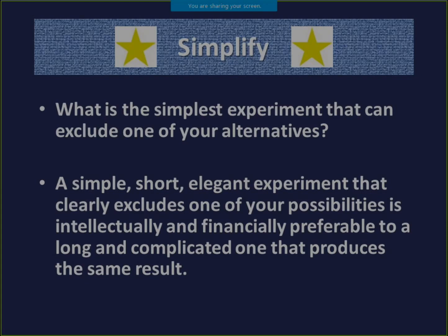For example, if you're mainly interested in how well a coating for silver can protect against hydrogen sulfide, then the first logical test would be to test your potential coatings on coupons of one silver fineness under exposure to just hydrogen sulfide. If a colleague notes that maybe application method also has an effect, so you should test three common application methods. And maybe there's a difference between fine and sterling silver, so add in that variable. And maybe we should also check on how the coatings perform on copper and lead too. And maybe metals of different geometries will vary, and so maybe we should try some curved coupons and some flat coupons. And what about trying to vary the coating thickness too?